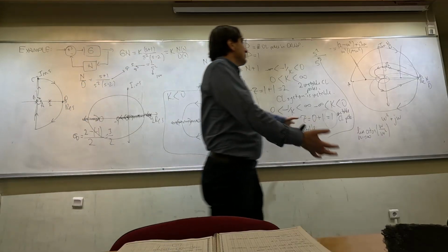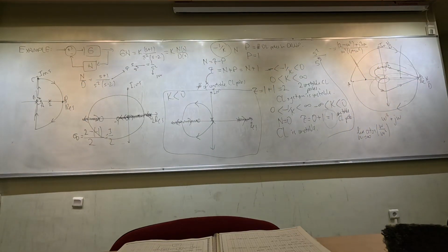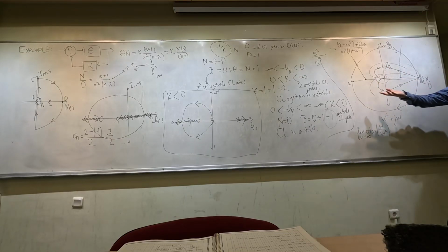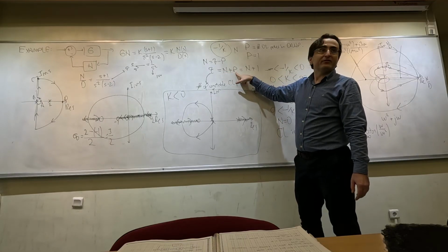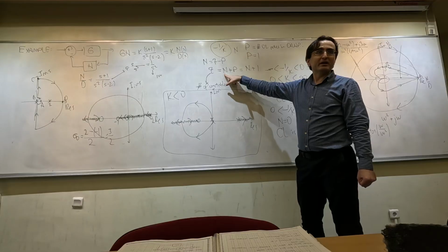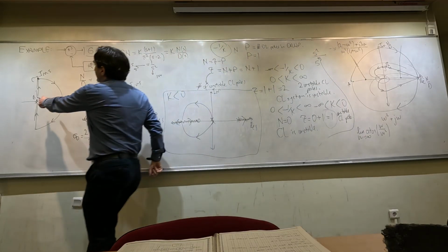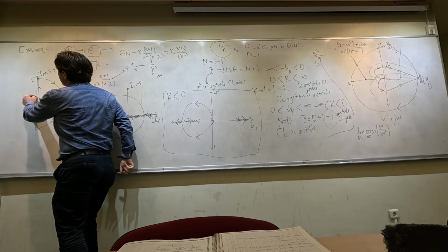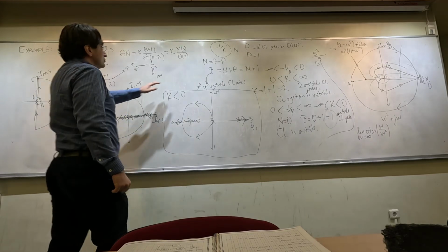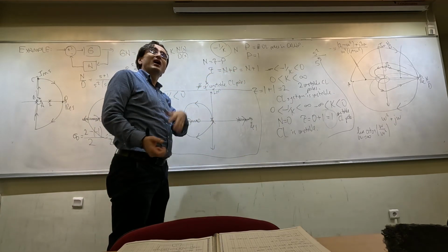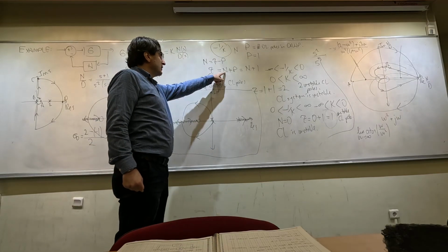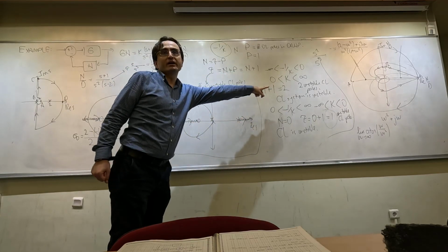Okay. And which parts of the Nyquist plot will be modified? These parts would all remain the same. The parts at infinity are going to change. And I will see that in order to get a similar result, when P is 3, N should be -1. Meaning that if you draw the Nyquist plot when you turn from this part, you would get the number of encirclements -1, meaning that -1 over k is going to be encircled in counterclockwise direction once. This is going to be -1. This is going to be 3.